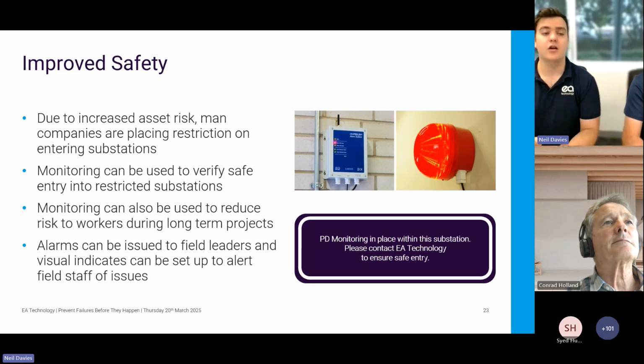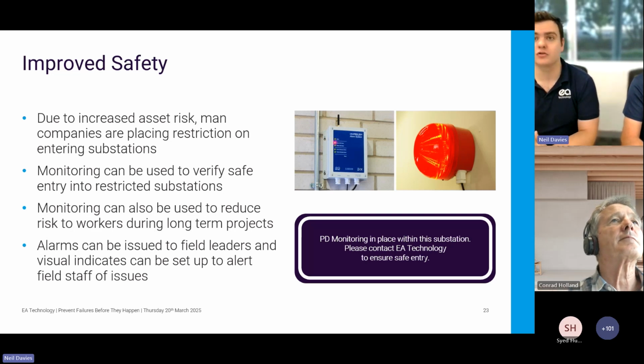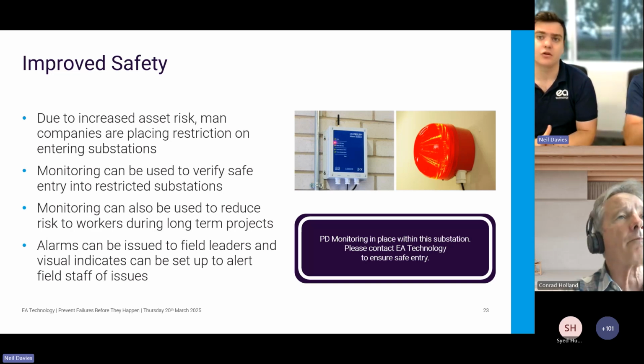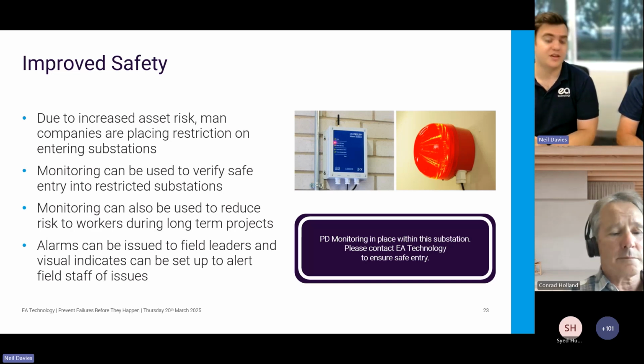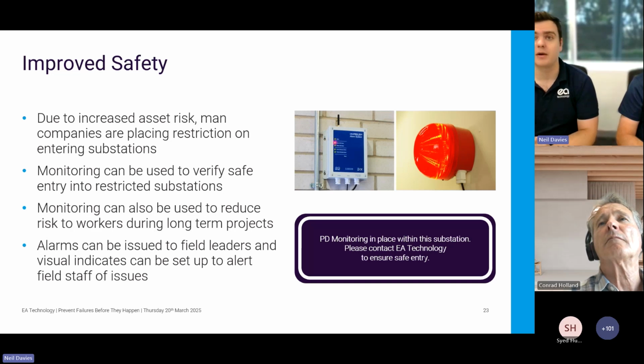Other companies are actually using the systems as part of extended monitoring during projects. So what we do is when they do have an extended project, I think anything over 2 weeks of a worker in a room with the switchboard, they install the system 2 weeks prior in order to get a good benchmark of activity within that room. And then they actually have us monitor the board on their behalf.